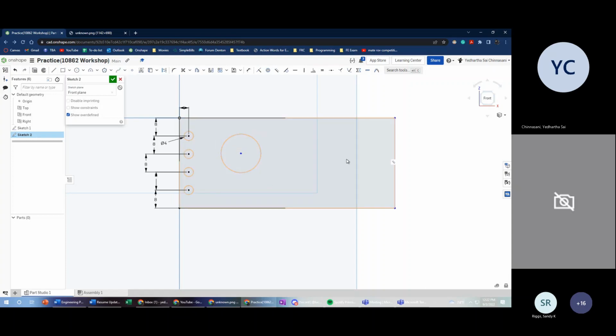The circle here is not defined. This line here is not defined. I can move this line over and over again. So just make sure it's defined. It's a strong warning, because if I see any of these practices in CAD, I'll be very mad, I would say. So the next thing is, yes, let's define this to this. Let's say 80 millimeters, right?